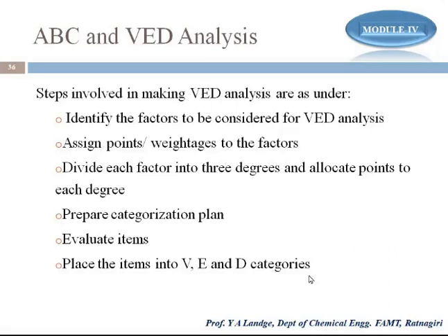Just like for event C, or work C, C depends on A and B, and we need to stay close to A and B. But out of A and B, again I have to decide whether to focus more on B or A. It depends on how much time they take. If event B takes 20 days, and A requires only 10 days, then you focus more on B. You control B more, because on the 21st day we need to start our C work.